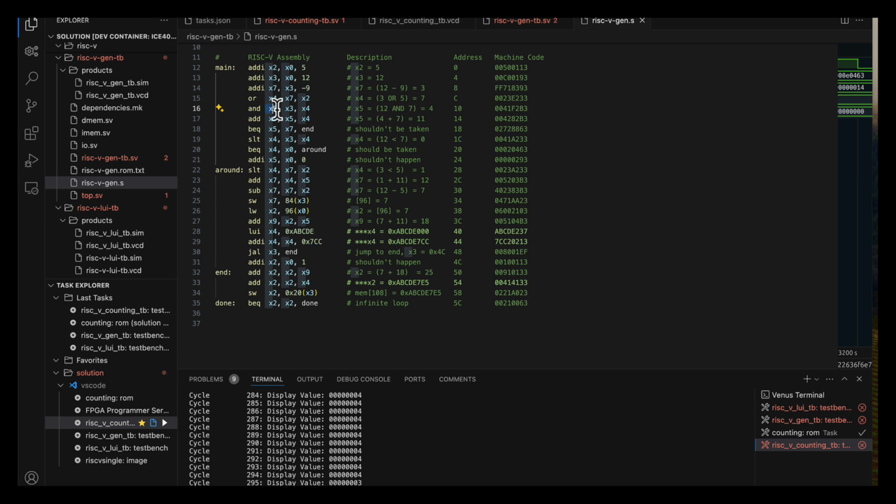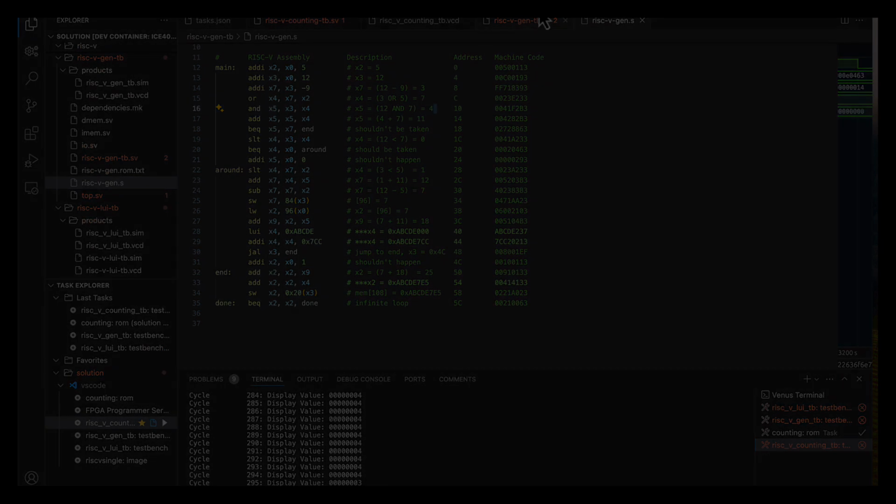And in that debugging mode, the value change dump, the Surfer waveform view, you can actually look and see, oh, in this step is the value 4 being written to register 5. You can look at the index of the register being written, confirm that the right index, 83, actually corresponds to register 5. Then you can look at the write data and confirm that it's the number 4. So it is possible to look at all of the details of what's going on and figure out where errors may be coming from.